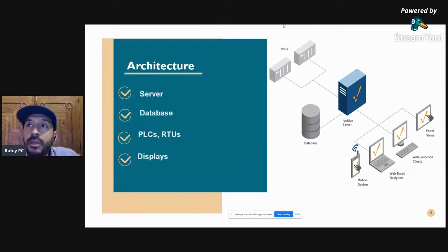Once you do have those, the PLCs are then networked together over a plant-wide network, just like you would in an office environment where you have a bunch of office computers. Instead of office computers, you'll be having PLCs. Those PLCs are then connected to a centralized server. Within this server is where the Ignition SCADA software is installed and runs. The SCADA server communicates to the database. Now, the beauty of Ignition is it can work with a lot of different databases, but primarily, most integrators would be working with either MySQL or Microsoft SQL Server. So those are the two primary ones that people generally use. But Ignition can run on MariaDB, it can run on Oracle, and a whole host of others as well. It depends on what the customer requires, but generally it's going to be MySQL or Microsoft SQL Server.